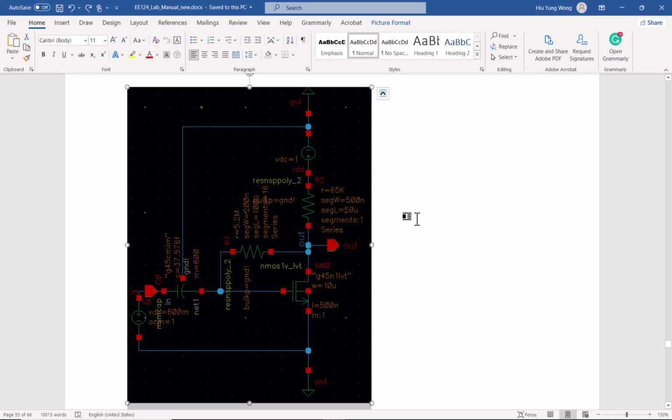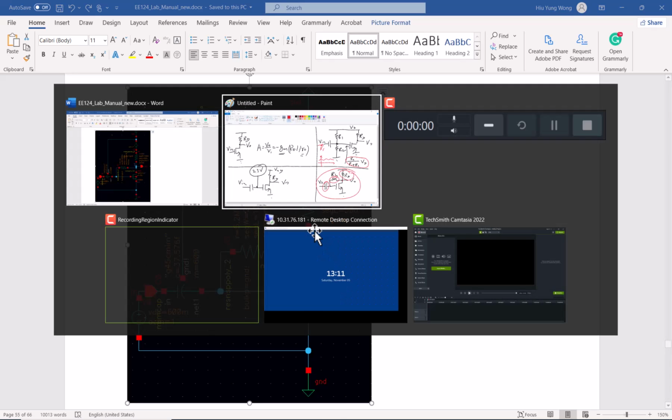This is the design that we eventually came up with. You see here we have a capacitor, we have the resistor, and this is VDD connected to ground. Particularly for the 65 nanometer technology, how do you make the capacitor and the resistor? It is not a simple thing, because some of them are actually a well resistor, so you actually need to bias the well to the ground also. So why is that, for example?